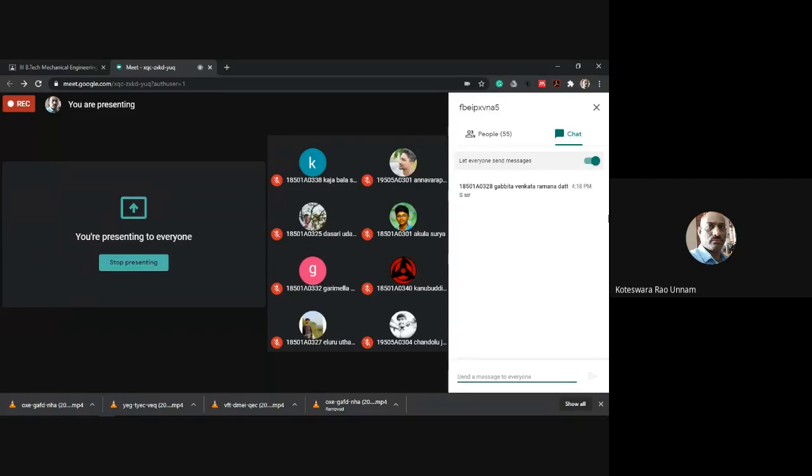Then you can see that in the next page we have design particulars on one side, that is the first column, and the second column has equations. In that he has given some formulas for boilers and axially loaded structural joints. Here the Unwin's formula is very important. We always use Unwin's formula to find the d of a rivet, that is the nominal diameter of the rivet. Similarly, in case of boiler, there is a formula for the thickness of the boiler plate. He has given all the formulas. Similarly, for the length of the rivet shank, he has given some definition.